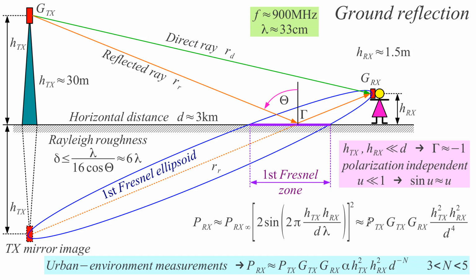So we could simplify these things, and what happens now is that out of our formula, the wavelength cancels out. We only have the height of the transmitter, the height of the receiver, and the signal decays not by d to the square, but d to the fourth power.